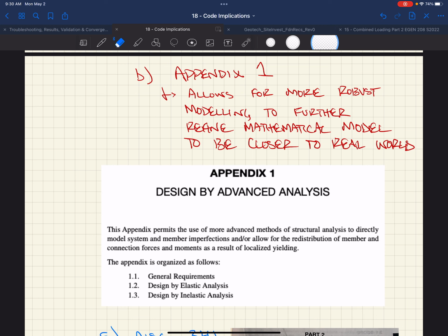It's going to be really stiff, or is it going to be flexible enough that we can negate it, right? We're going to say that our member displacements are going to be small because we typically maintain that they're pretty small, right? We don't want to see them with the naked eye. And so it's not going to go through a whole lot of rotation, but all we want to know is that in that small amount of rotation, how stiff is that connection? But you can directly model that if you knew what that was. They're saying, hey, doors are open, go for it.